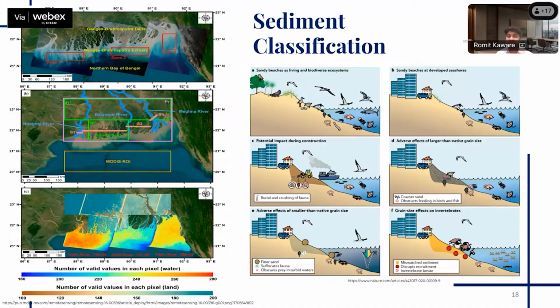There are various empirical relationships developed through which we can relate the spectral data to the suspended sediment concentration or to the turbidity. A lot of spectral indices are being developed to map this satellite information to the suspended sediment concentration. So it provides a very macro range, as we can go over a very large spatio-temporal range to classify the sediment with varying timescales as well.